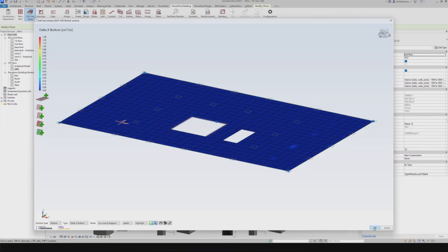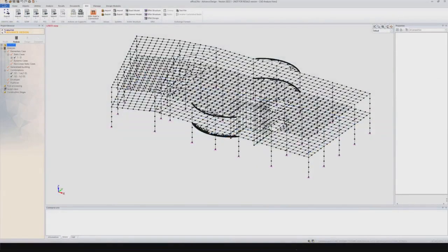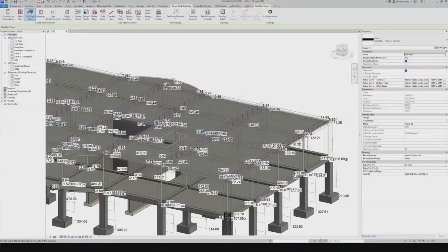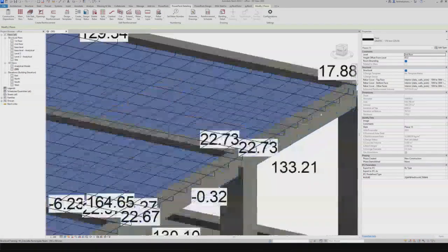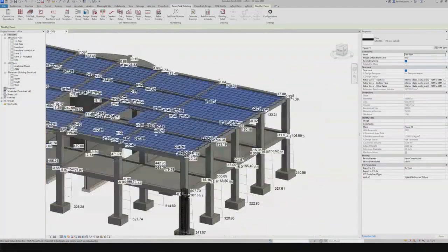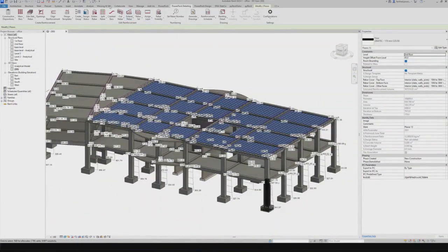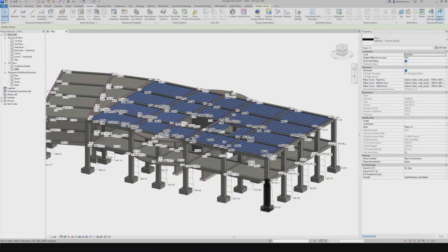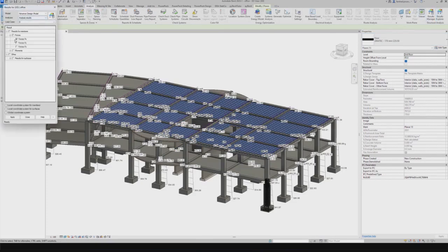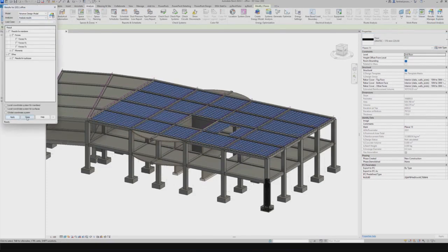go back to Revit. It's generating, and there you go. I have my rebars created for my bottom layer of that slab. We can actually perform the same scenario. Just here, I will hide my diagrams so it's going to be more clear, as you see here, the rebars.